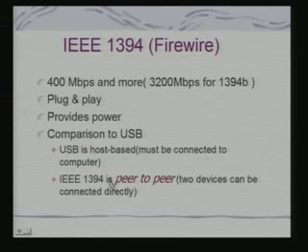But in comparison to USB, the basic difference is here. USB is host based. That means there has to be a computer to which a client device is connected. But IEEE 1394 is a peer to peer protocol. Two devices can be connected directly.